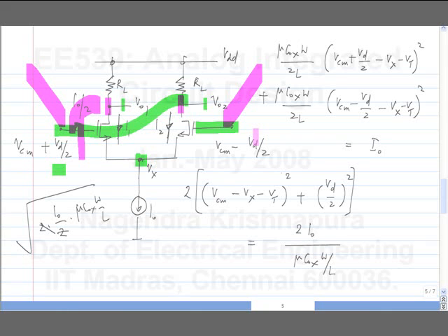So this whole thing is known as the line of symmetry. Because you raise things on one side and reduce things on the other side, and because of the symmetry of the circuit, in whichever way the left side voltage affects this point, the right side also should affect it in the same way. And the only consistent solution is a 0 gain. Even without the details of the circuit, you can figure it out. It's for any circuit. Again, the circuit has to be fully symmetrical.